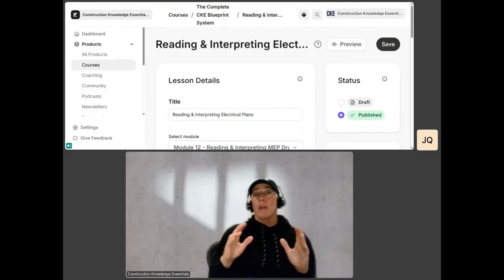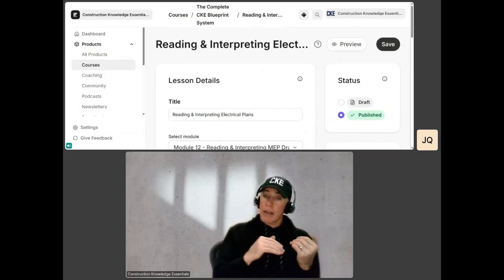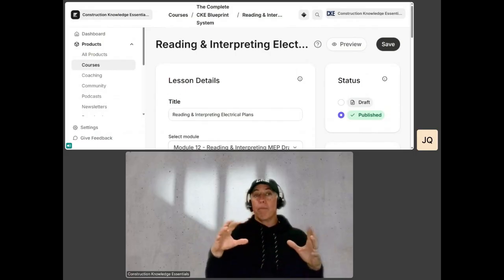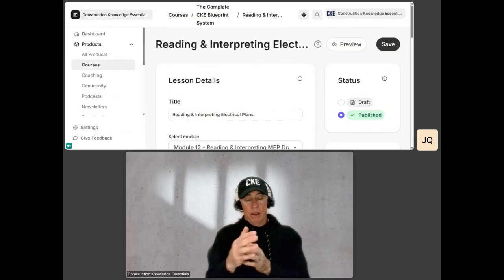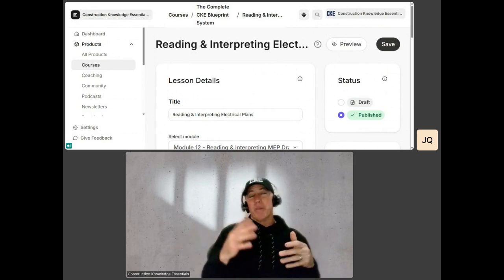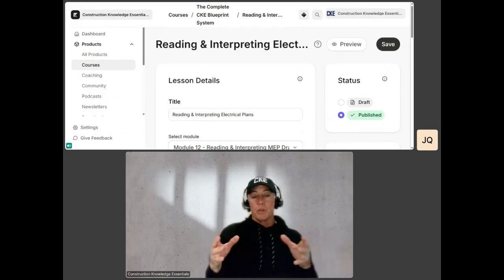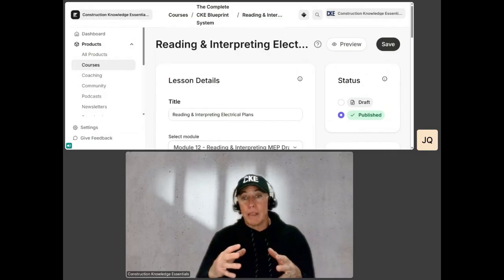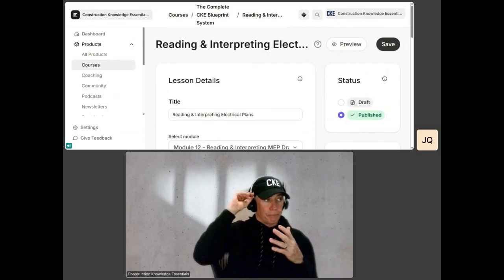We usually like to do plumbing first. Why? Because plumbing has a pitch to its drain, so it needs to have its direction first. It also is, when you're setting up plumbing, you have plumbing in the shower that has to be centered. You don't want something that electrical goes by, which usually wouldn't happen. But let's say your lighting, let's say over the sink, you usually have those things. Or, and many times, it depends on who's in the building or who's in the structure first. We would usually like to,